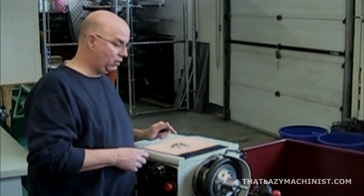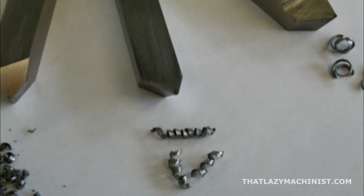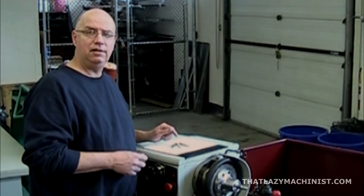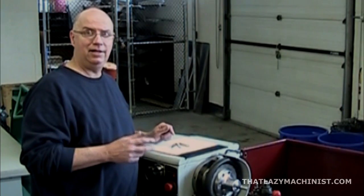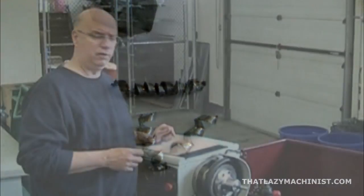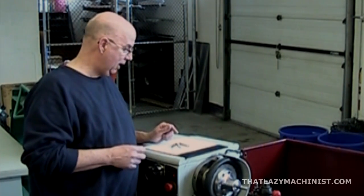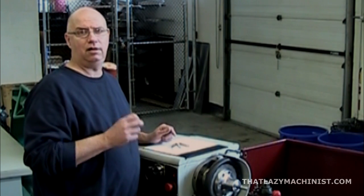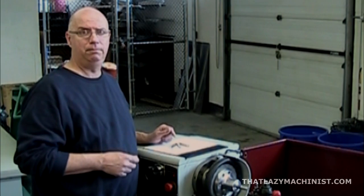Our second tool, the one in the center here, is our tool with a neutral cutting surface. We can see that the chip has a nice tight curl to it and that it is a continuous chip. The chip also has a nice color, very bright and shiny on the inside of the chip and very slightly dull on the outside. This is probably our best chip.